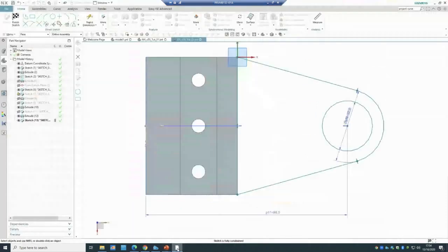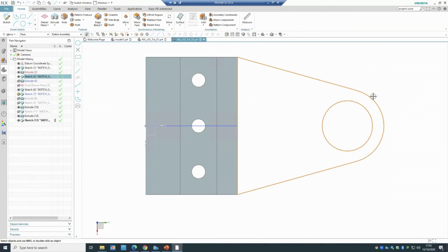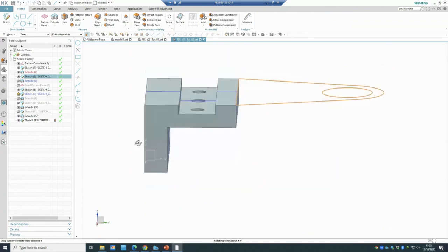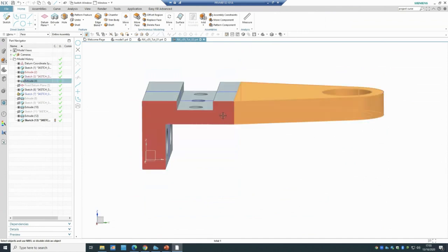You make those, and you just make that line and create those two lines, but make sure once you create them, they are tangents. Once you're creating the line, if you do it like that, do you see that? It automatically gives you the option to make it a tangent. Then you do a trimming. Once you've done the trimming, if you come out of the sketch, you have something like that. You just need to extrude it onto the other plane.